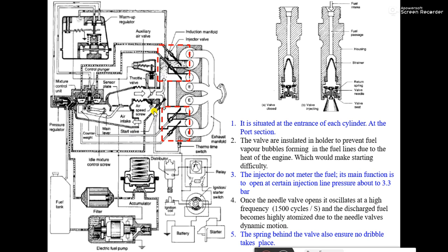In the case of the K-Jetronic system, it is there. But if we talk about the D-Jetronic system or other kinds of L-Jetronic system, then the service injector alone plays the role of the starter valve. The K-Jetronic is a very early development of the injection system. In those days, they used a separate injector to overcome the cold starting problem. But nowadays, no separate injector is used to overcome the cold starting problem. They came up with a solution to the cold starting issue by integrating that purpose into the service injector only.